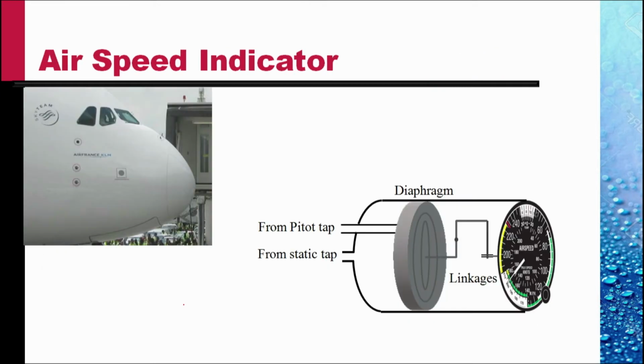For measuring the airspeed of an aircraft, we need a pitot pressure, but we also need a static pressure, a pressure in the atmosphere which is not disturbed by the presence of the aircraft. It is a difficult proposition and various methods are used to pick up the static pressure. One of the more common methods is to have static holes on the nose or near the nose of the aircraft in the fuselage of the body.